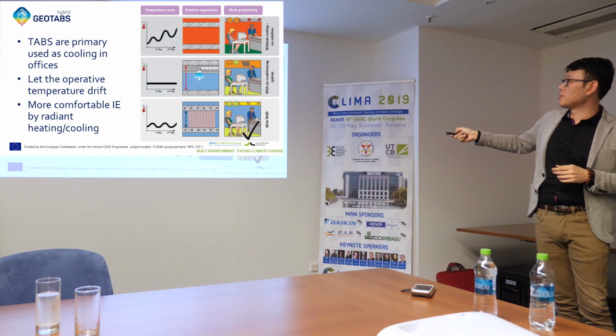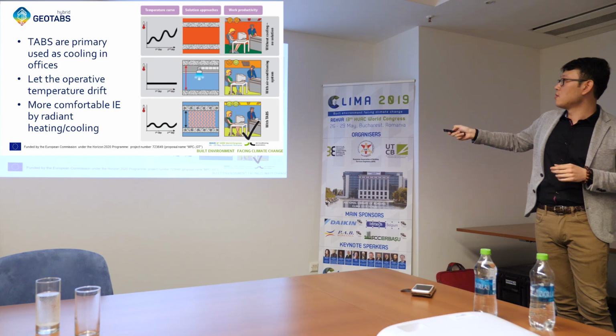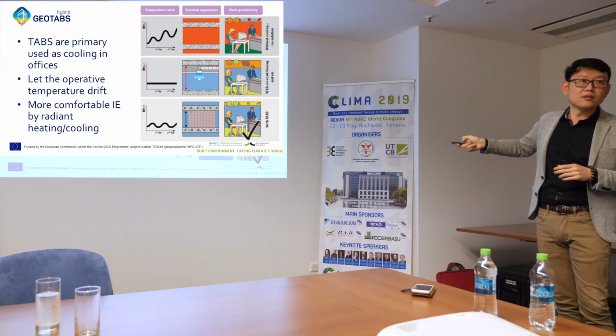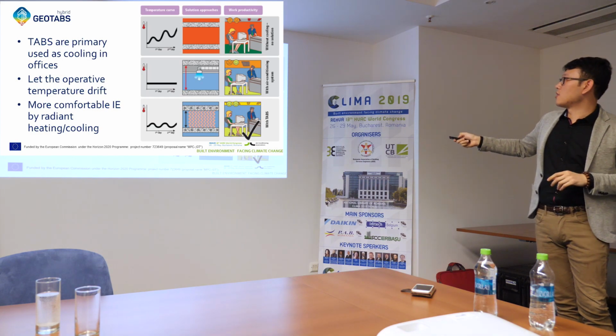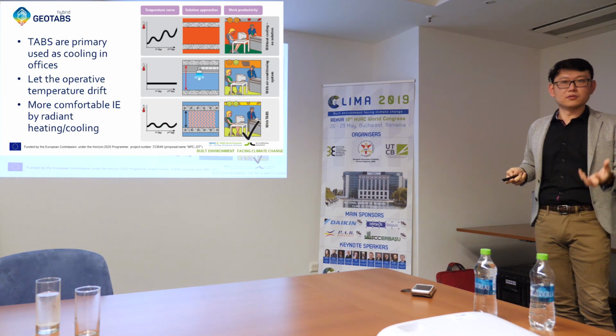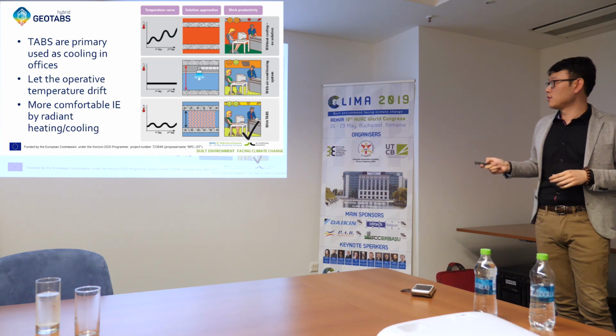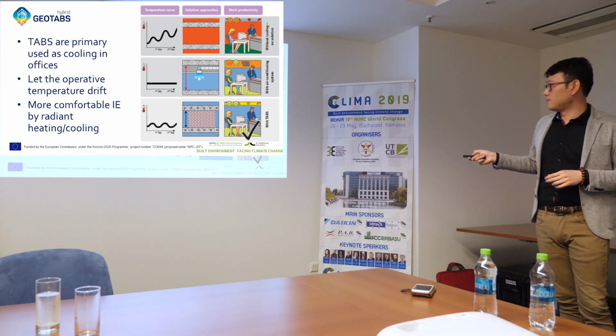The second one is that we have some kind of AC system, an air conditioning system. We have the convectors here. Of course, you need certain heights to put the vents there. Yet sometimes people suffer a little problem with draft or cold effect. You don't feel that much local comfort. So the third one is TABS.